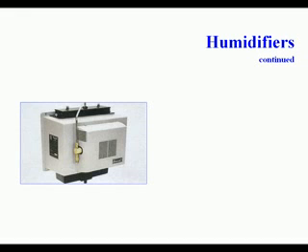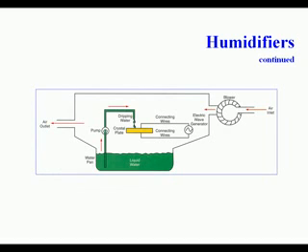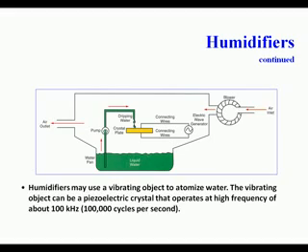Evaporation takes place as the heated air passes through the evaporator pad. The pad is wetted by water metered through a solenoid valve. Water that is not evaporated flows to the bottom of the humidifier and is drained out. Humidified air is returned to the heating system and enters the living area. In this unit, it has a small fan motor and a solenoid water valve.